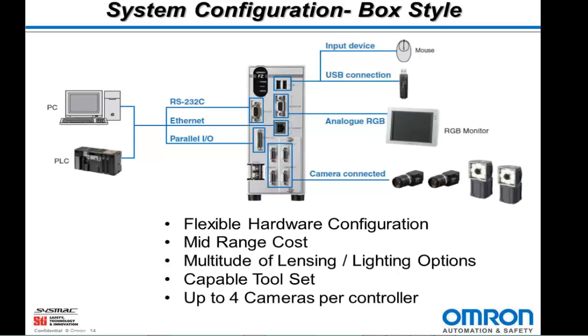So in the next configuration, this is essentially a box-style controller. So different vision companies go to market a few different ways. Some are of the belief that everything should be consolidated into the camera itself. Omron historically, and now we have a little bit more diversification, but historically has taken the stance of, we'd like all the smarts to be in our controller, which is safely placed in a control cabinet, and then we keep the lower cost, somewhat dummy camera, for lack of a better term, out in the exposed environment. In the case that something potentially happens, it's a lower cost replacement for the customer.